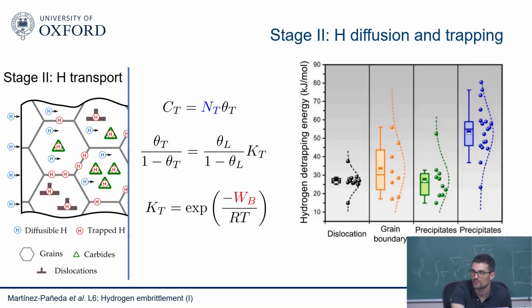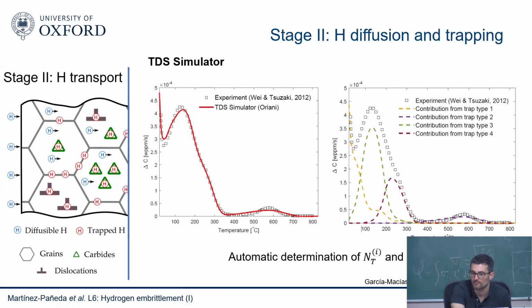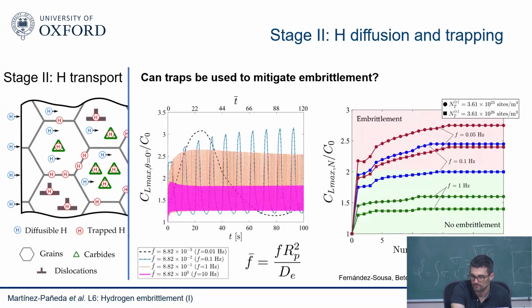And another question is that when you talk about the trapping characteristics, it depends on the binding energy as well as the hydrostatic component. So when it comes to carbides, because of the misfit at the interface, which one dominates? Whether it is the binding energy that dominates the trapping characteristics of carbides, or the stress? So you're thinking because you're going to have a raise in stresses, then hydrogen will be attracted to it in addition to being attracted by the trapping as well.